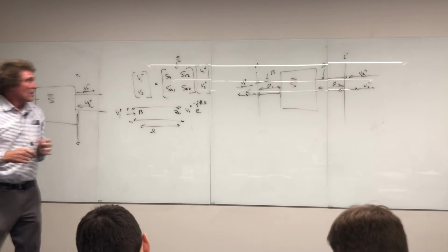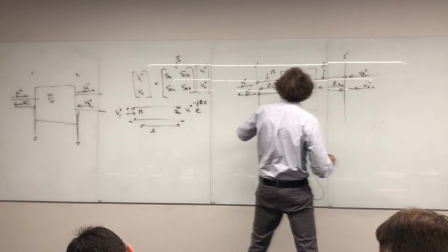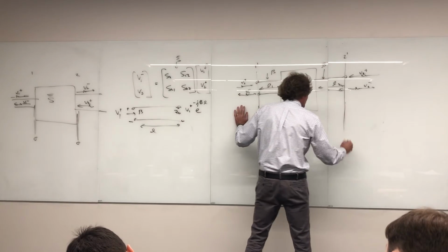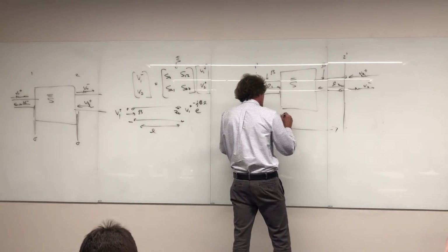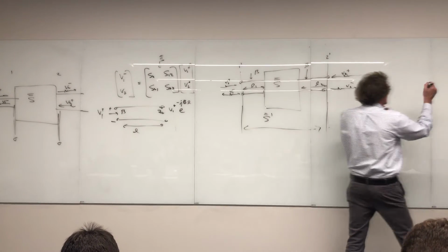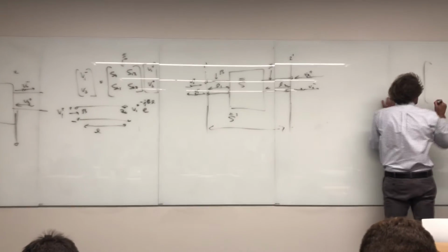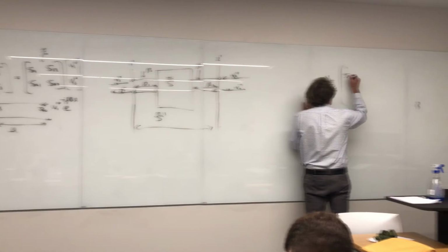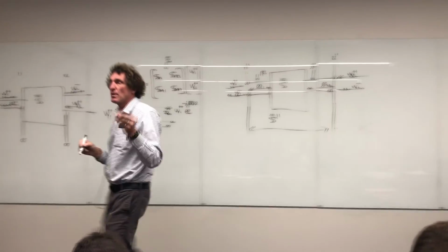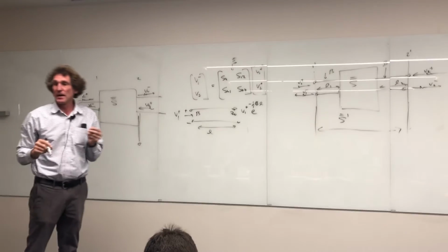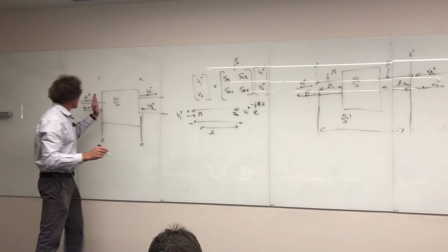Now, when you look at this, and we recreate the matrix here, this matrix that's going to be from here to here, defining these S parameters, we'll call it S prime. Now when I look at that, my S prime, and this is in the book, my new matrix will be this, and I'll explain this. Put down S11 first. Now that's the reflection coefficient, it's the ratio of V1 minus to V1 plus, correct? So V1 minus to V1 plus, assuming you're right here.